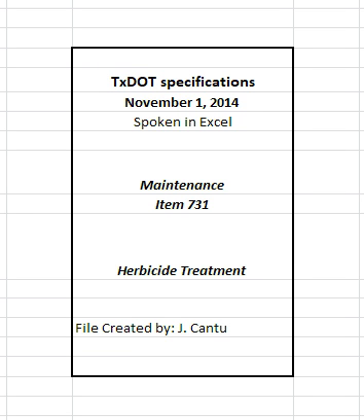7.2.2 Guardrails and cable barriers. Spray a band of herbicide approximately 18 inches wide under guardrails and cable barriers. 7.2.3 Appurtenances, retaining walls, sidewalks, islands, traffic barriers, mow strips, attenuators, etc. Spray a band of herbicide on and along the outside edge of appurtenances and approximately 6 inches of vegetation along or around the fixture.